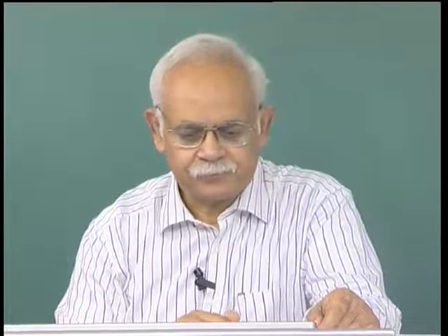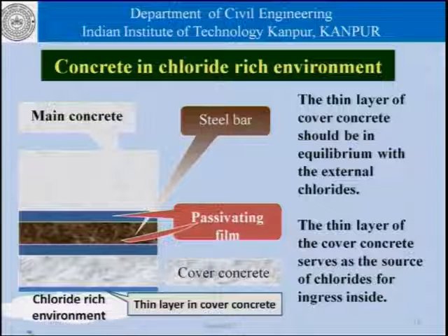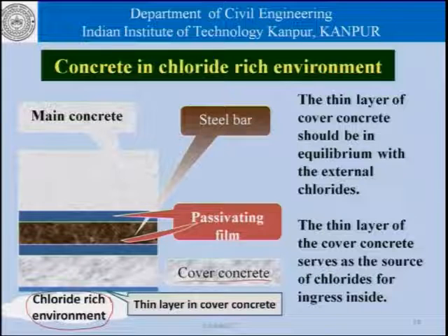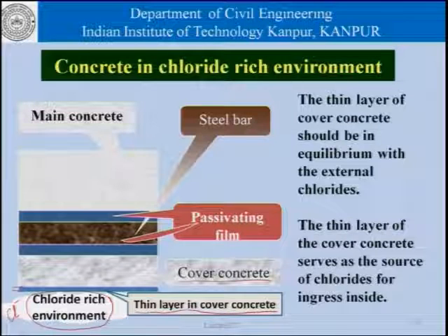Now, let us take a look at the concrete in a chloride rich environment a little more closely. We have a cover concrete and we have a chloride rich environment outside. There has to be a physical equilibrium between the chloride content in the atmosphere and the chloride content in a thin layer of cover concrete just outside here, which is near the surface.